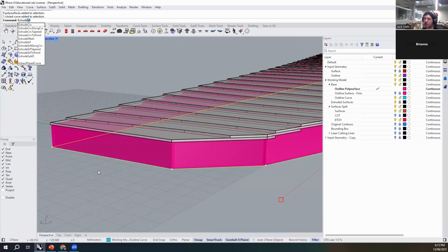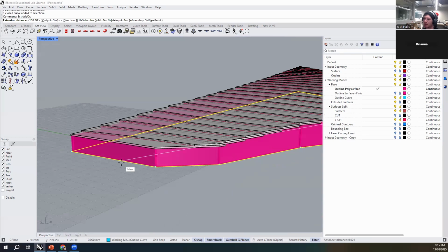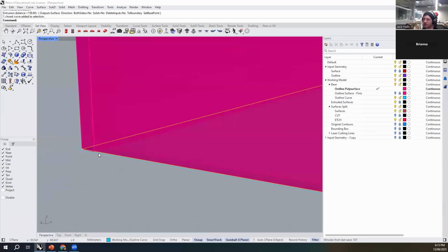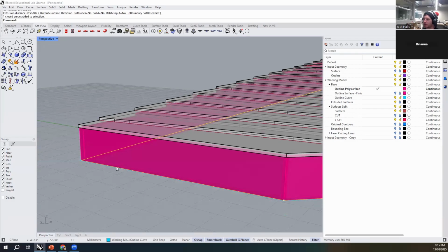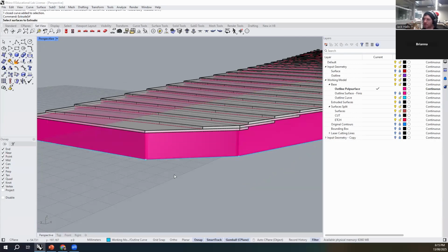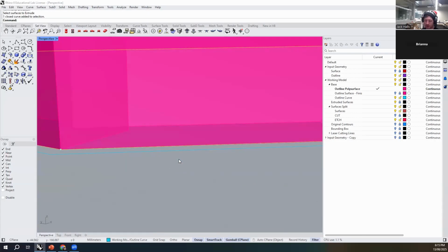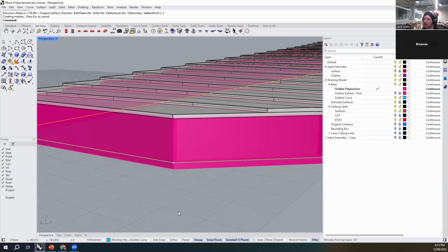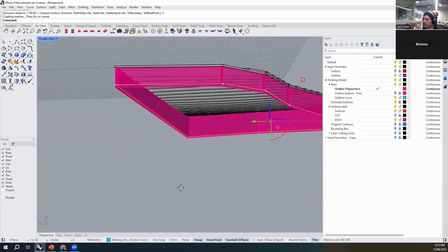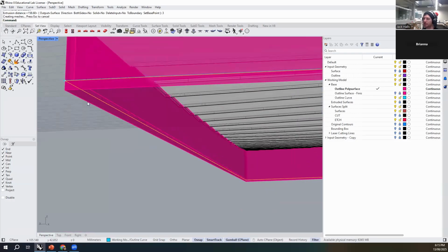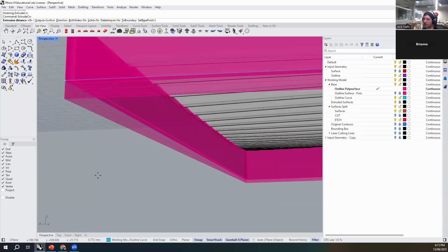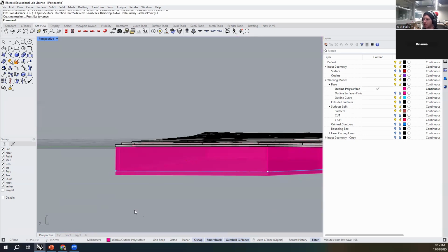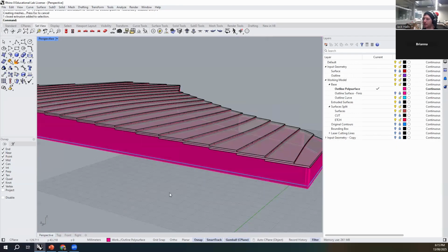I'm going to say extrude CRB. That's going to give me an incorrect one. I wanted this offset version. Not that offset one. One that's a little bit smaller. Right. Extrude CRB, perfect. And again, it's just 3 millimeters, just like before. Oops. So I didn't have my input selection correct there. It was set to not solid, so we do want to change that to solid. Okay, so now we have a base component as well.